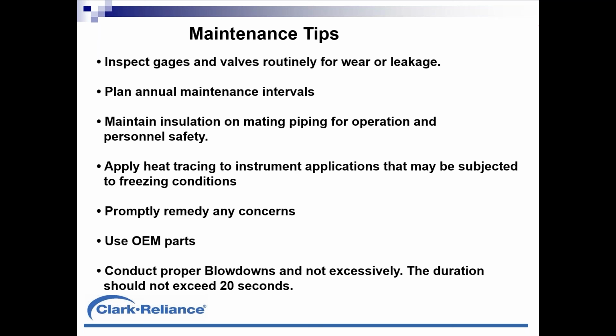Use OEM parts for any instrument you have. The OEM knows best as far as any updates, changes to gasket materials, changes to specifications they may make, and most importantly, torque values. If I under tighten a level instrument such as a gauge glass, it'll leak ahead of its time. If I over torque the fasteners on a gauge glass, I could cause damage to the glass or short service life. So it's very important to follow procedures.